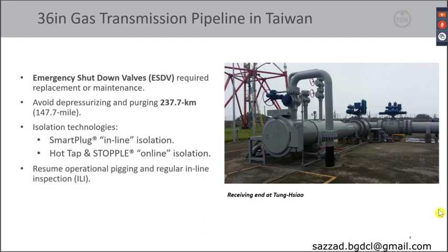The ESDV and valves on the production T at the Yong'an required replacement of the seal rings on the valve flanges. At the Tongxiao, the ESDV, which is the valve immediately after the receiver shown at the picture here, had to be completely replaced, and a corroded branch line needed to be removed from the pipeline.